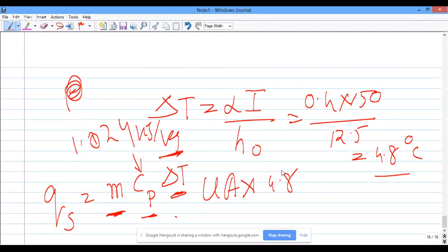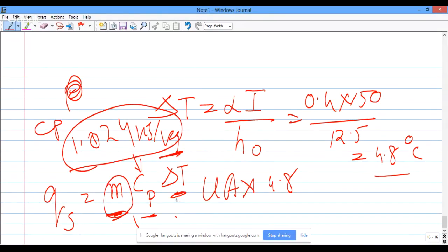So that's how we can calculate the sensible heat gain if 1.2 kg of air is coming in per unit area, per unit time. So it's simply CP, which is this, mass is 1.2, and delta T is the temperature difference, 36 minus 27, so one can find it out. Right? Okay. Any other question in the meantime?